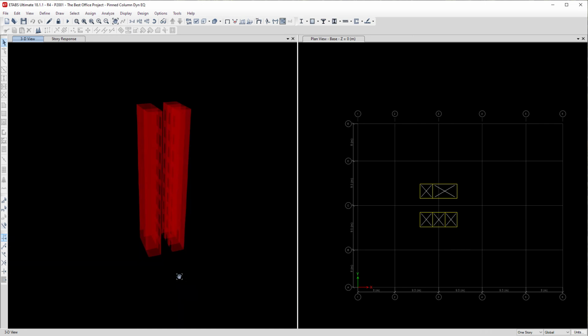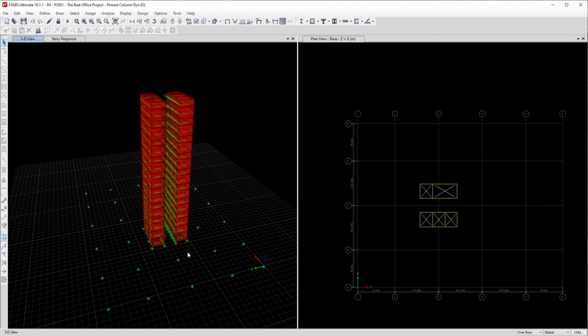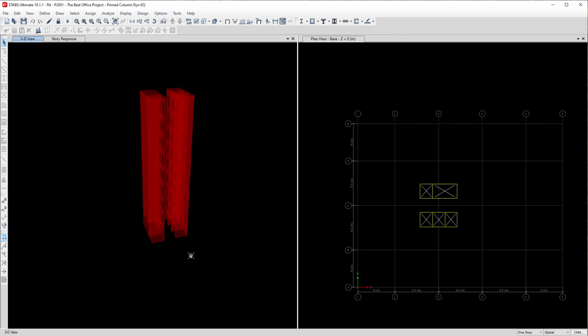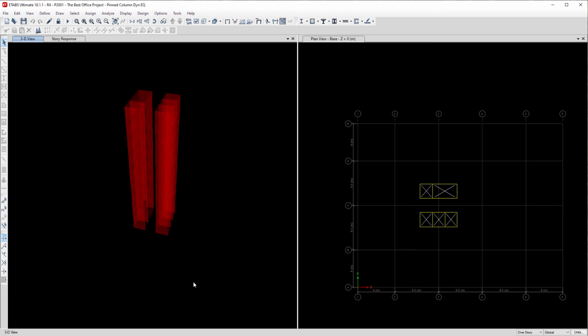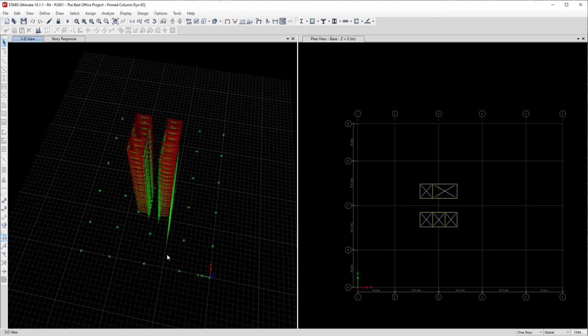And that's why you can have the same exact building and you can end up with two lateral stability designs. One of them might seem heavier than the other one, or depends how you look at it. The other one might seem that it may not work, but they're both compliant to the code. One is designed to the static earthquake and one is designed to the dynamic earthquake. But obviously, I prefer to always take the dynamic analysis for earthquake for that purpose, and I'll leave it up to you to choose which one you want to go ahead with.